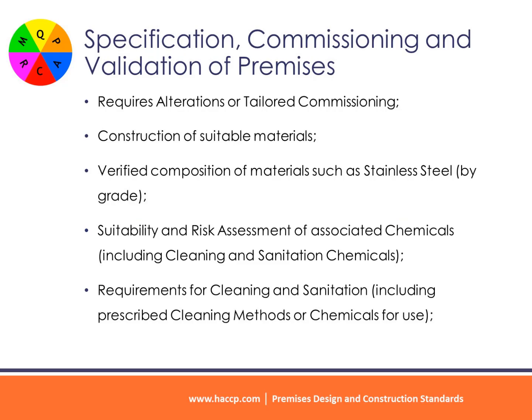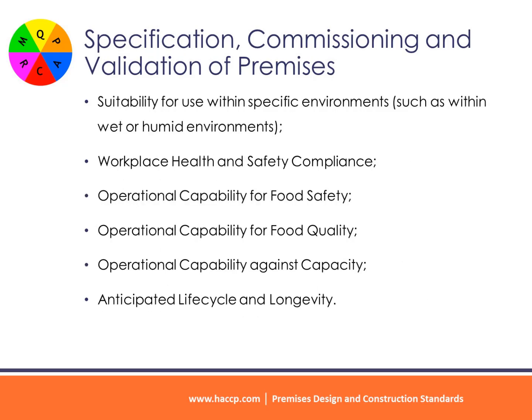Construction of suitable materials. Verified composition of materials such as stainless steel, by grade. Suitability and risk assessment of associated chemicals, including cleaning and sanitation chemicals. Requirements for cleaning and sanitation, including prescribed cleaning methods or chemicals for use. Suitability for use within specific environments, such as within wet or humid environments.